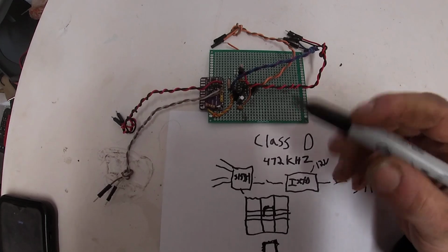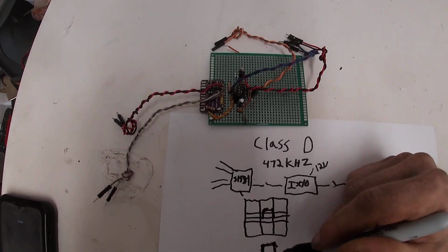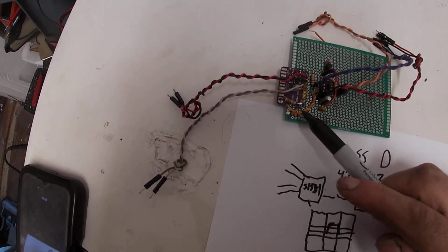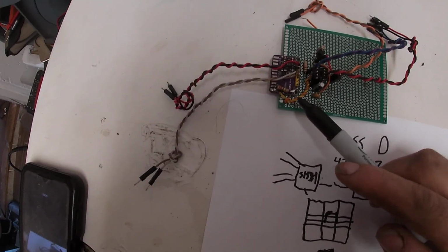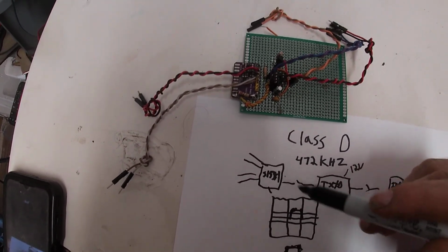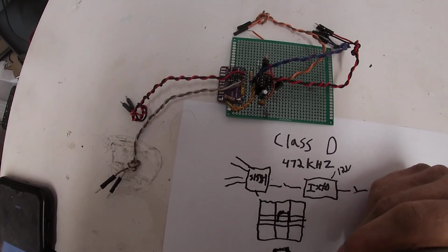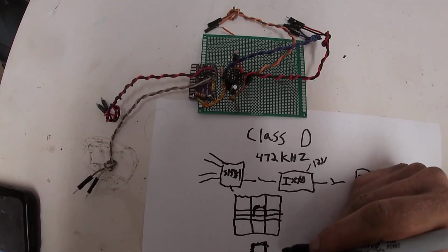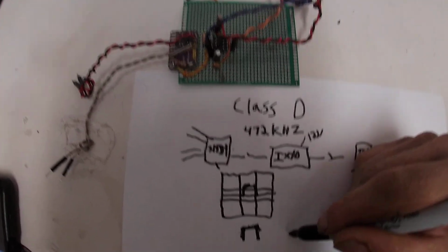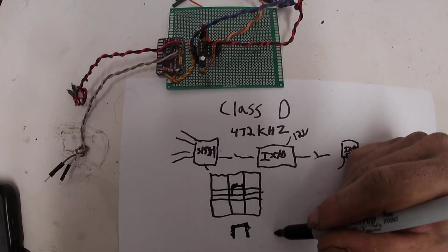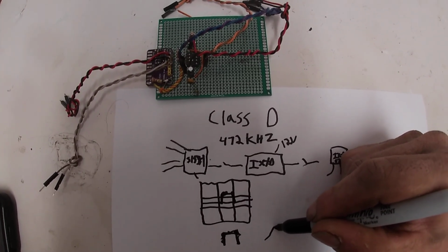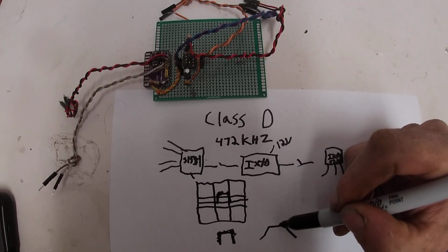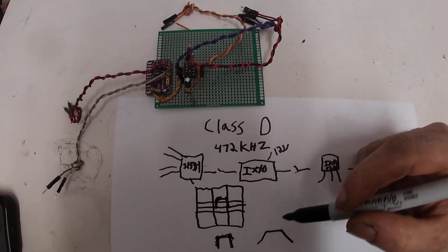Well, to solve that, we're going to add a little resistor that protects the SI 5351 and slows down the fast edges. So after that resistor, we end up with something that looks more like that. Still a square wave, but just kind of with rounded, tamed edges.